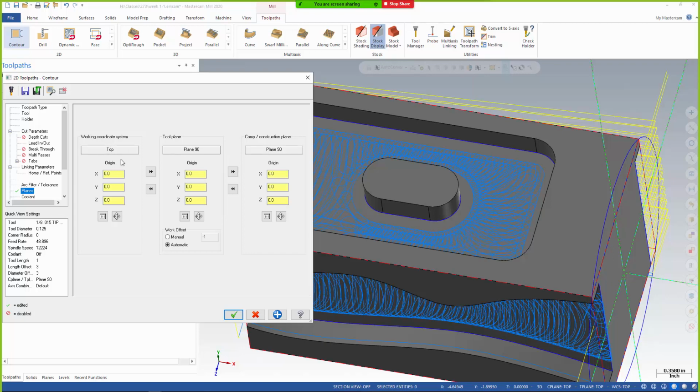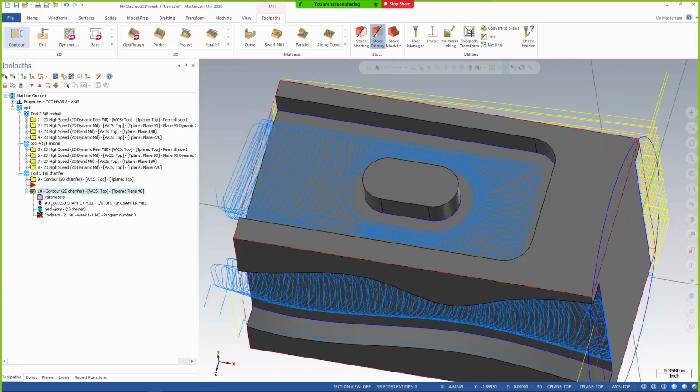Okay, this is what differentiates or tells Mastercam we need to rotate. Otherwise, if these all stayed the same, Mastercam wouldn't rotate the axes at all. It would stay at A axis 0 and try to run whatever you programmed on the wrong face. So once that's all set, then it's just a matter of reassigning the geometry.